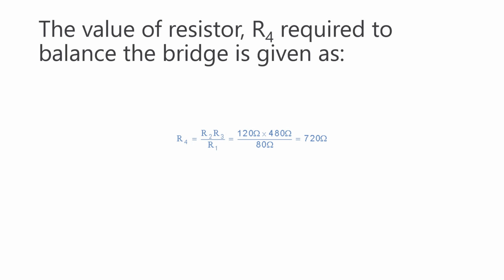The Schering bridge is for measurement of capacitance and is used to measure insulating properties. The Wien bridge measures unknown frequency. Among the DC bridges, the Wheatstone bridge finds the unknown resistance value, and the Kelvin bridge finds unknown resistance values less than 1 ohm.